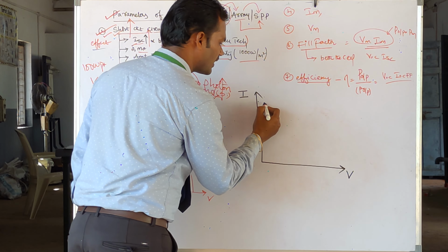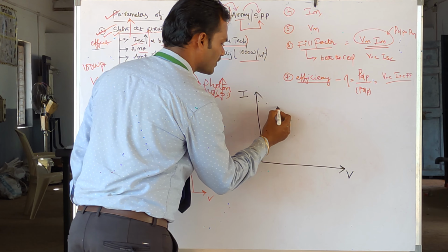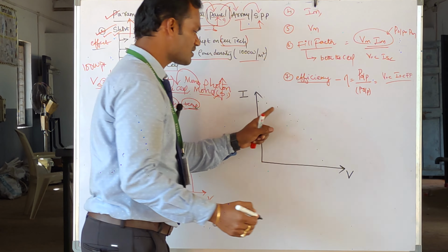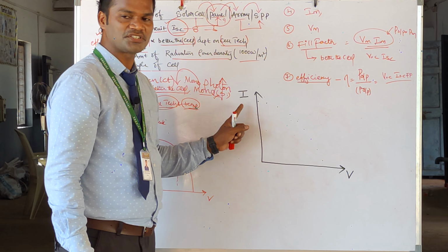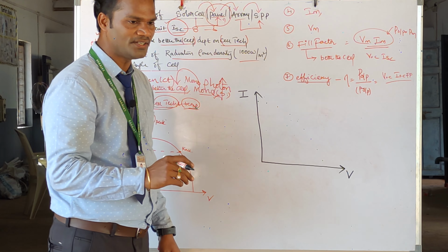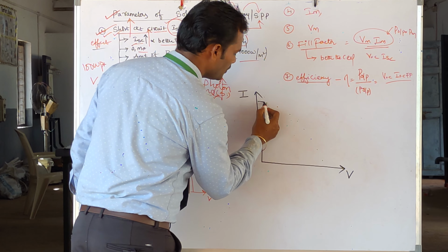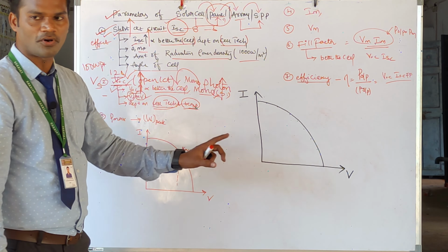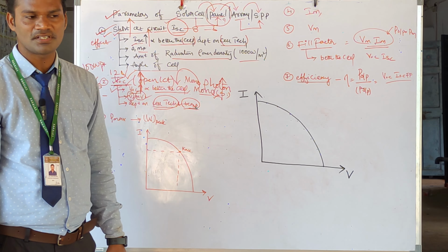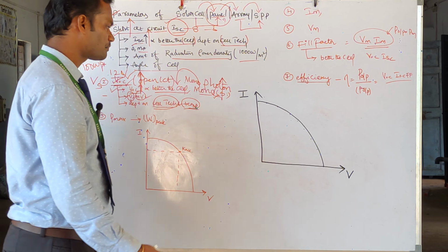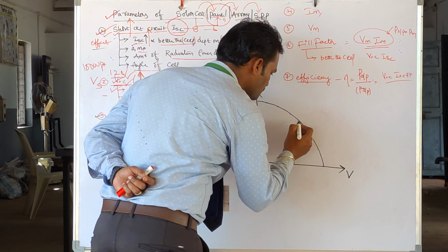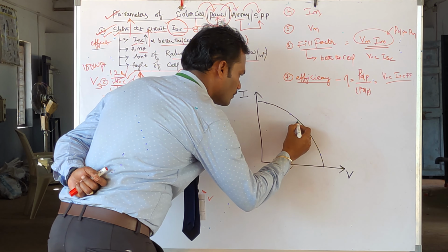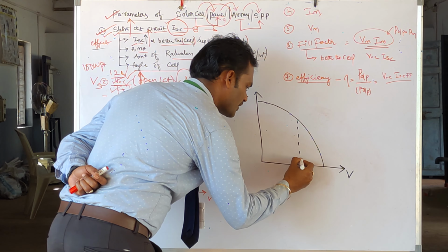As the time is changing, automatically the solar parameter will change like this. These dots are nothing but voltage and current measured at different times and different radiations. I'm just joining all these points, which is going to develop a structure. Now on this curve we need to identify which is the maximum power rating. I'm marking one point to make it clear.